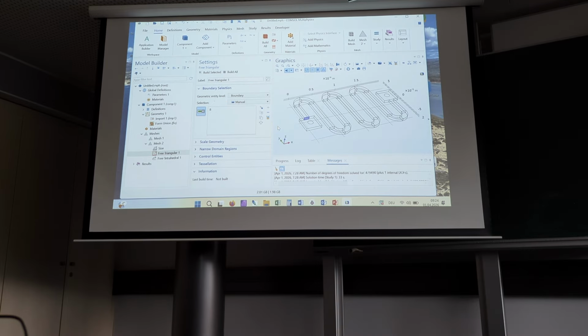But that is a special case, how I know it's 8. I mean, you can display all the numbers that you might find out, but I want to show you a more general approach, which I'm sure is very useful for you. Maybe I can have your attention for that thing. Here is something which is called click and hide. Click and hide, like the name says, you can click in the structure, and by clicking it disappears. It's not deleted, it's just for the purpose of displaying, it's disappeared. So the idea to get access to that cross section, which is now not possible, is to click and hide away that inlet. So we first enable click and hide.